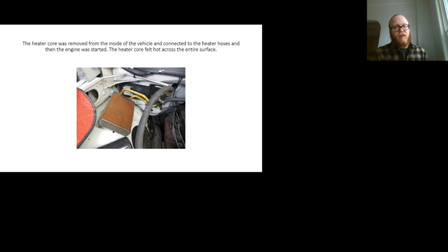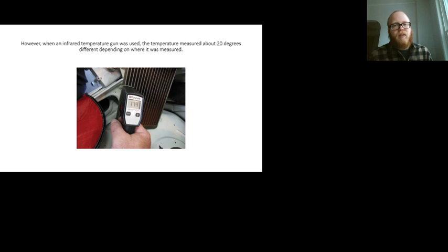He goes and tests the heater core out of the vehicle, because this person must be hourly and not flat rate. But they're testing it and they're able to see that there are hot and cold spots in it, so it's definitely plugged up.